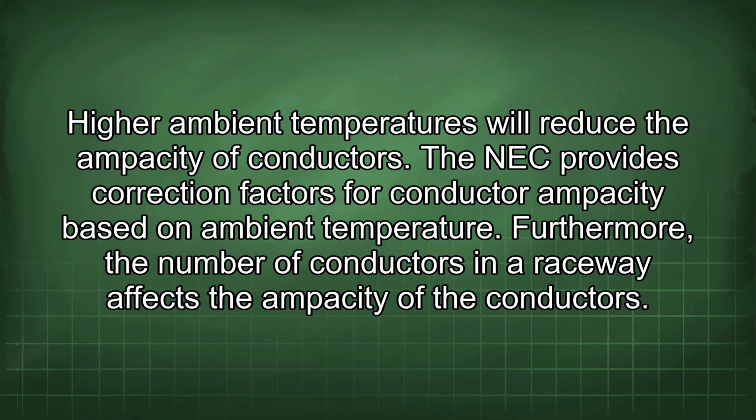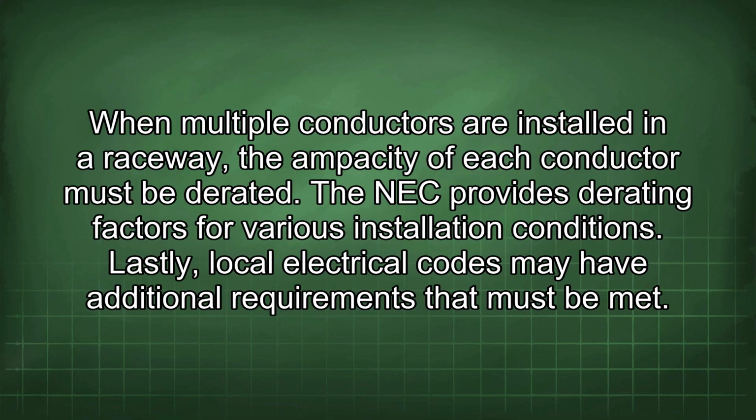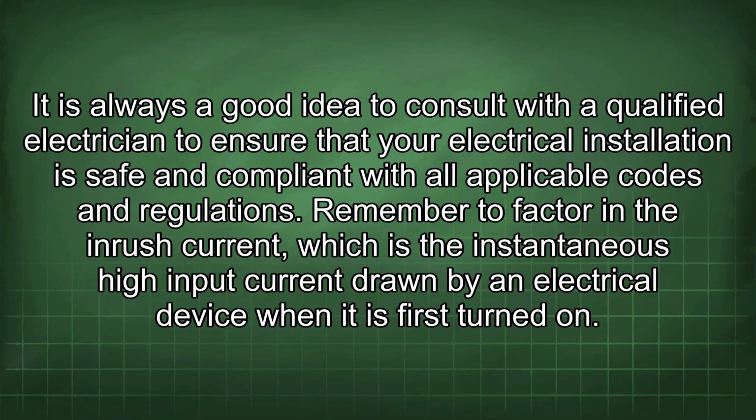Furthermore, the number of conductors in a raceway affects the ampacity of the conductors. When multiple conductors are installed in a raceway, the ampacity of each conductor must be derated. The NEC provides derating factors for various installation conditions. Lastly, local electrical codes may have additional requirements that must be met. It is always a good idea to consult with a qualified electrician to ensure that your electrical installation is safe and compliant with all applicable codes and regulations.